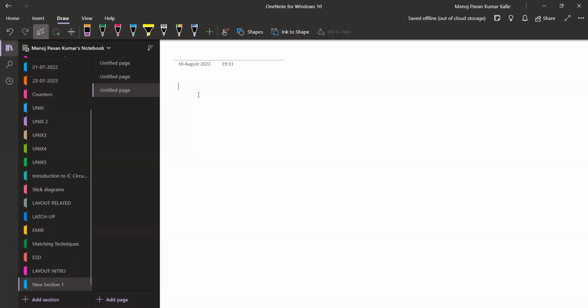Sir, excuse me, let me complete. We have to go for the post-layout simulation to know whether the layout is working correctly or not. After post-layout simulation, we will be able to know how efficiently it works, because whatever output the schematic gives, the layout will obviously not give that efficient an output. There will be some degraded output, but how much it is degraded, we have to check.